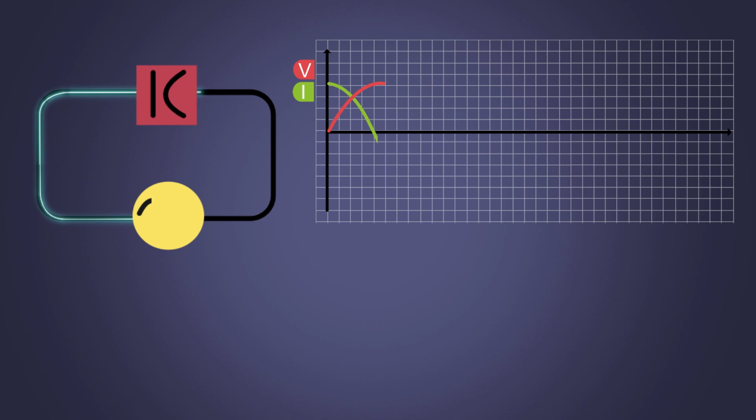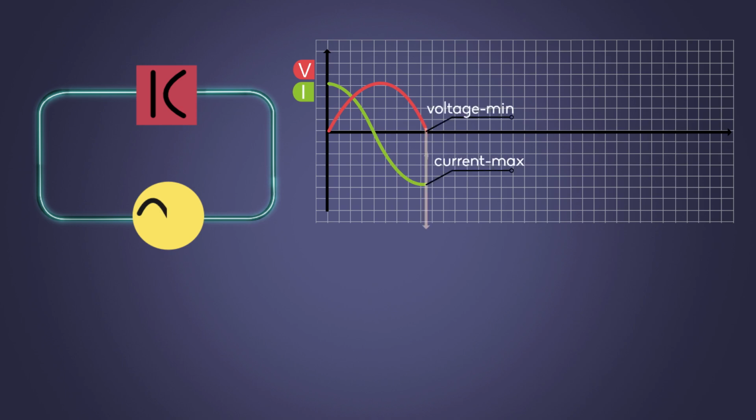As the applied voltage begins to decrease to 0, that is from 90 degrees to 180 degrees, the slope of the voltage is negative. So, the capacitor discharges in the negative direction. At the 180 degree point, along the line, the rate of change of the voltage is at its maximum again, so the maximum current flows at that instant and so on.